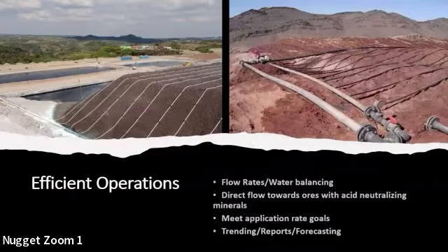We also looked at percent clay, percent passing 100 mesh, and some of the Atterberg results. So we looked at correlating it to a number of different physical measurements. But what we found is that correlating it to the PSD indicator provided the best relationship, with an R squared of about 0.82, which we're seeing here in this graph.